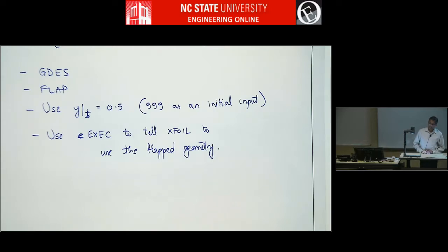Yes? I just had a question. I don't know if it's been answered yet, but in pplot, I think it's option 4 is to save the plot as the PostScript file. It just saves automatically as post.ps. Is there a way to change that, or do I have to include that in my batch file to just rename it afterwards? Yeah, so I saw your post and I went and looked at pplot. I thought there used to be some option, but maybe I'm not remembering correctly. So it looks like there is no option to specify a file name. So just write a little batch file or MATLAB file to, every time you run pplot, go and change the plot.ps to something else that you can keep track of.